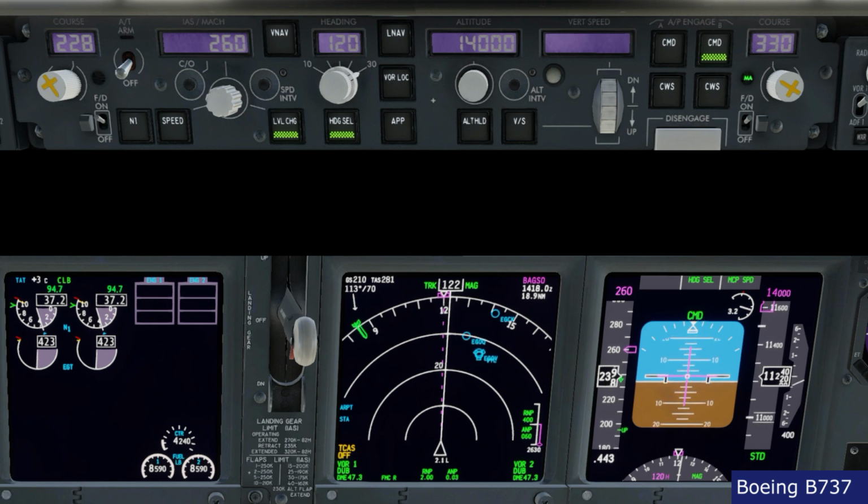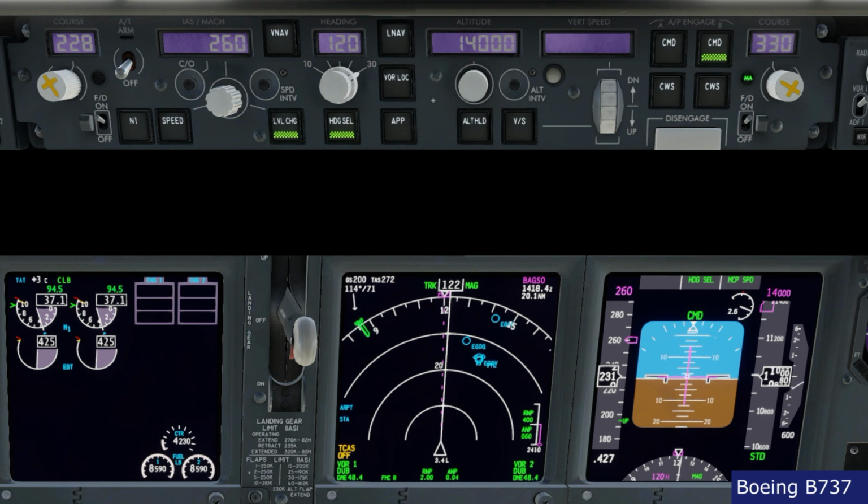So it could be that in level change the aircraft started descending, as it's doing now. You see the aircraft started descending, because in order to recover the speed we have to descend. So that's a correct functioning of the level change. As a matter of fact, you see the aircraft is trying to reduce as much as it can the rate of descent, but it's losing the speed, and the only way to avoid losing speed is to keep descending. So it will eventually even increase the rate of descent and will continue descending.